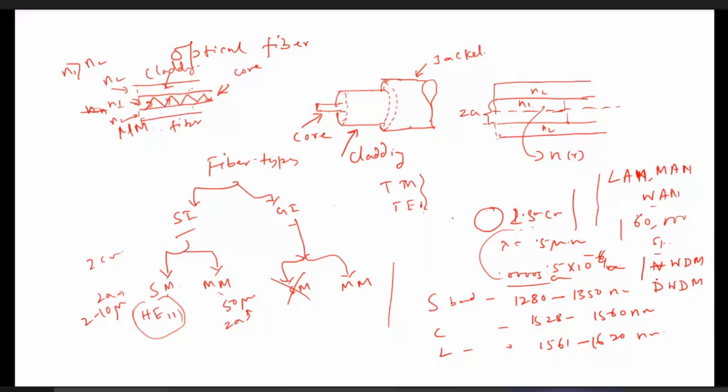Many carriers can be transmitted through the same fiber. Generally, a communication system needs one carrier. For optical fiber, many such carriers can be transmitted. So 100 carriers can be transmitted. That's what is called dense wavelength division multiplexing. Very similar to frequency division multiplexing, but in optical regions it is wavelength division multiplexing. Also, there can be soliton communication systems using optical fiber. In detail, you'll see it in the optical fiber communications subjects.